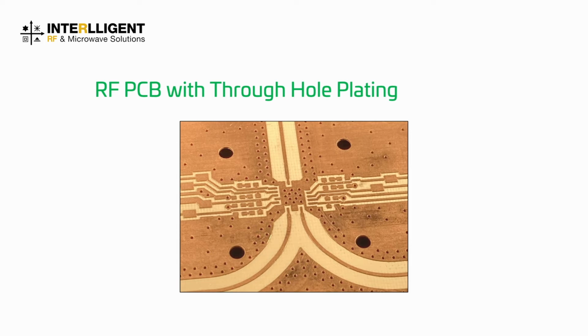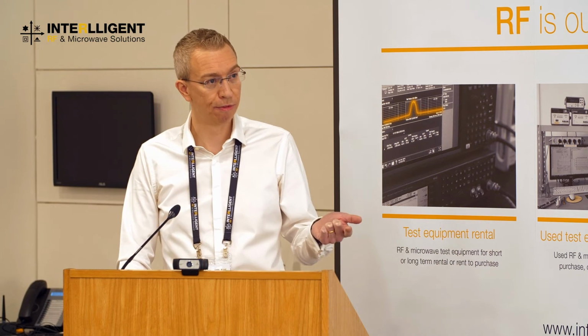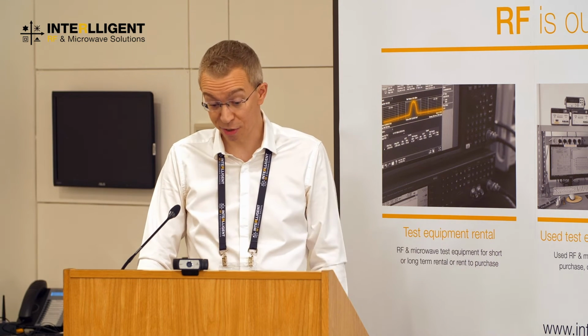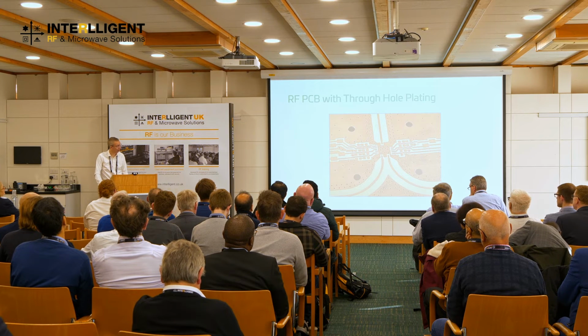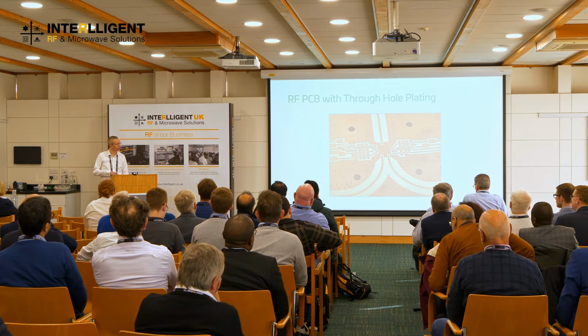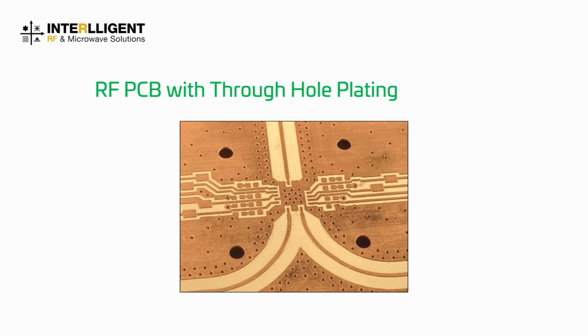So the PCB is then put back on the milling machine and we do the isolation routing. And ta-da, we have a PCB with effectively as many vias as you want at no extra cost to you. The great thing is that these vias provide good electrical and thermal conductivity, and they'll survive the repeated reflow of putting QFN parts down and taking them off again, which is really great. And impressively, this plating process only adds about an hour to the PCB manufacturing time. So you can quite literally, within a 2-3 hour period, go from nothing to a fully plated PCB that you can put parts down onto.